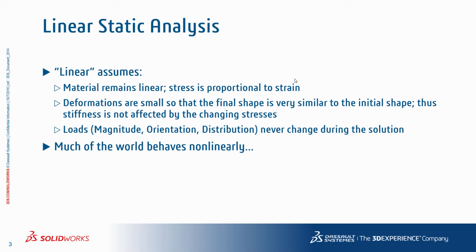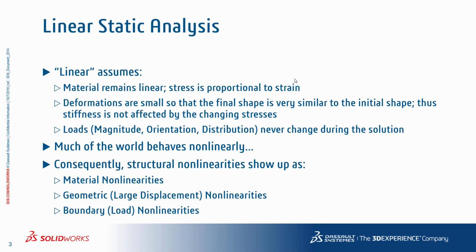However, much of the world behaves nonlinearly, which means the above assumptions may no longer hold true. Consequently, structural nonlinearities show up in the material behavior, such as plasticity effects, elastomeric effects, and so on. The geometric stiffening or softening of the structure as it deforms is another common nonlinearity. And finally, the boundary or contact, where the physical interaction between surfaces can alter the rate of load transfer between parts depending upon the loading area, is also a common type of nonlinearity.